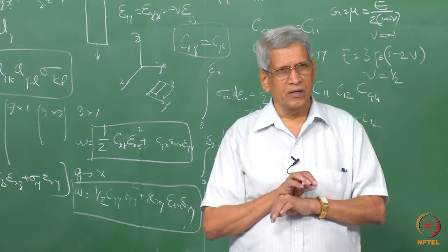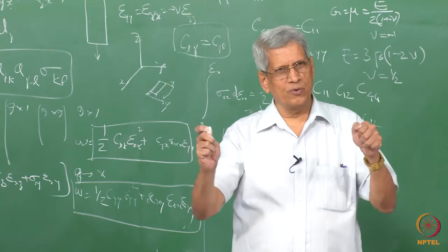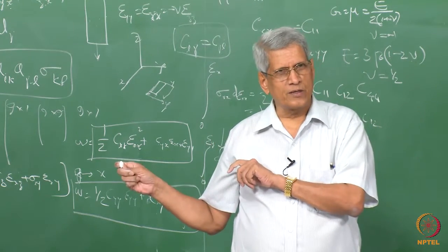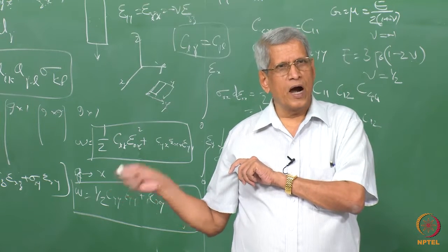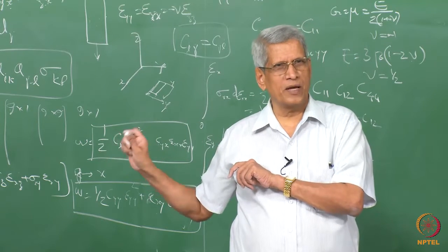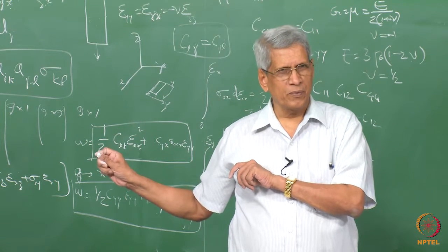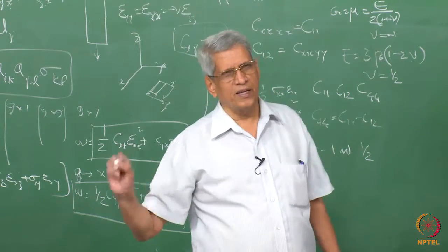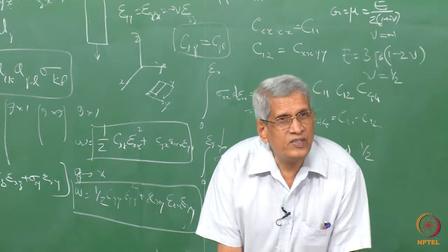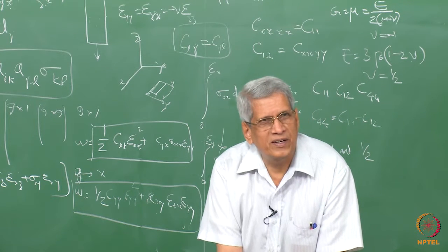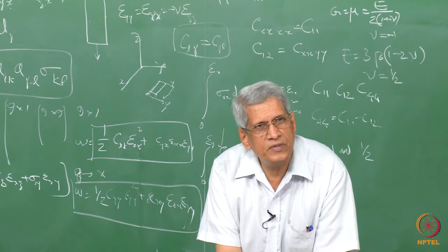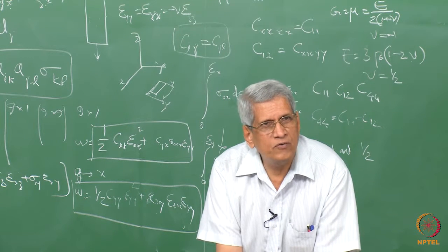If you try to do any separation in one direction, in the other directions also the bonding is going to be changed. If we take the second derivative of this bonding energy, it essentially gives you the stiffness constants, and how much it is going to be affected in terms of contraction. That is what nu represents.